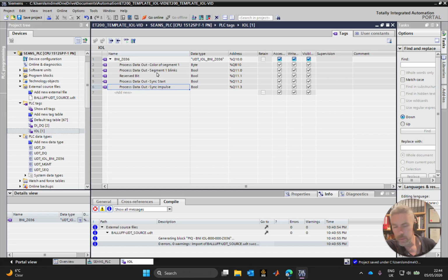You'd say, well, how is that so obvious? How would you catch something like that? Well, it is something you just need to keep an eye on. When you do IO-Link, it's organizing your data in the same way that you would otherwise have to organize your digital inputs, digital outputs and memory bits. It's just that in a lot of cases with non-offsets or optimized data blocks and the lesser requirements for addressing, we're getting spoiled and taking it for granted that addressing will be looked after. It's not so much the case all the time, and this is a lovely instance of where you could get caught out very easily.